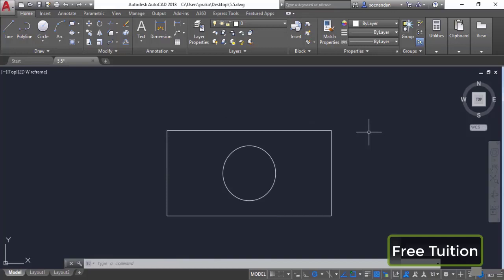Now using grips, you can also modify your geometry in many different ways. For example, on the modify panel, we have multiple tools like scale, stretch, move, and copy or rotate, and we have used these tools from modify panel. But instead of selecting them from modify panel and using them from here, you can directly use the grips and use them. Now in this case, we have this complete geometry. Let's say that we want to modify it using the grips. For that, I'll select it. Now select the grip which you want to make as a base point. So I'll select this grip as the base point, and now click on it.